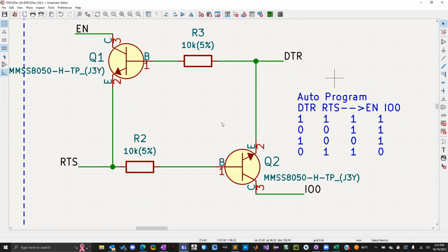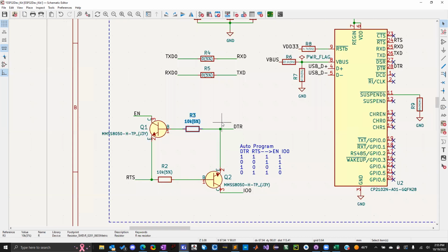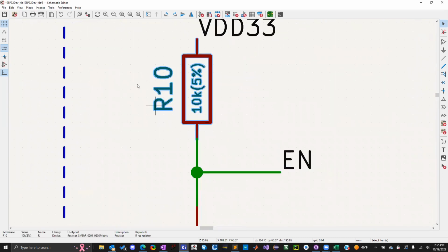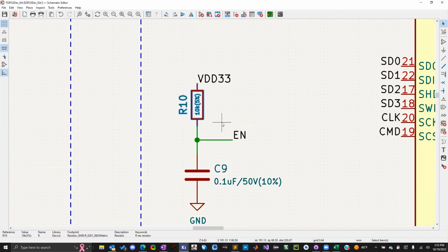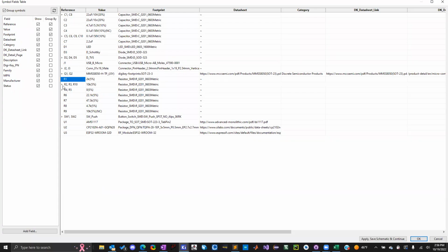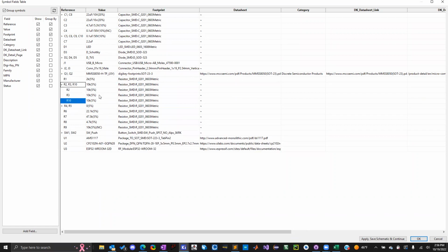I'm assuming your art's in the very first command. Right here. Why? So they're numbered differently? They have the same values, but they don't group them together. Only 2 and 3 are put together. Yeah, I noticed that too, some of these are not grouped in the same place. Double check your footprints, because the only reason it would separate it is because the value isn't typed exactly the same, like if you have a space or something, or if the footprint is different. That's the only reason it would separate it in that table. Did you have a space or something?